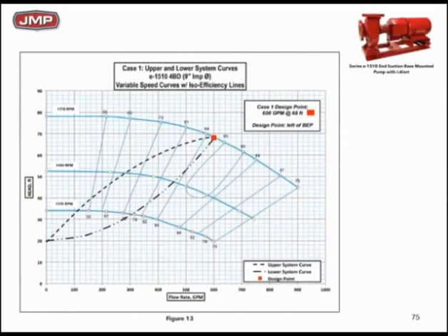We are too. So here's the message. Can I pick it to the right of BEP and maybe pick up a pump efficiency a touch? Yes, I can. But I'm living dangerously, and you best be sure you got the right pump head. And that's the issue. You got to make that decision.